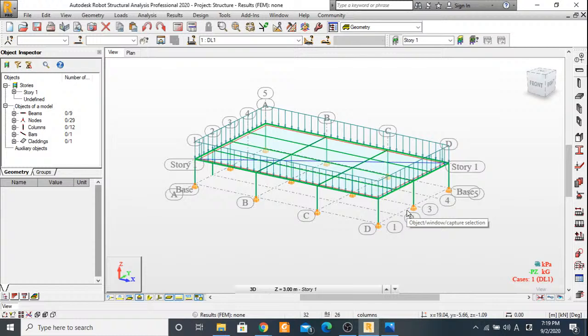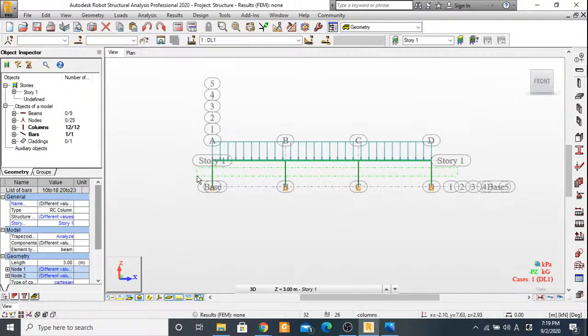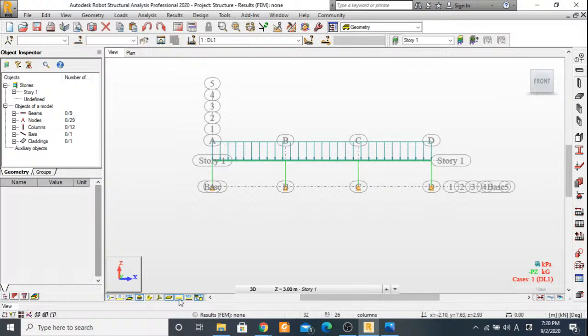All right. Unfortunately, as I explained in the beginning, the weight of the slab here includes part of the beam. All right. So we need to make sure that we add the weight of the downstand of the beam, which is the part of the beam that's not included in the slab, linearly on top of every beam. All right. So for that, I will select all of the columns. Okay. We'll select all of the columns. Let me do that selection again. Let me remove the load.